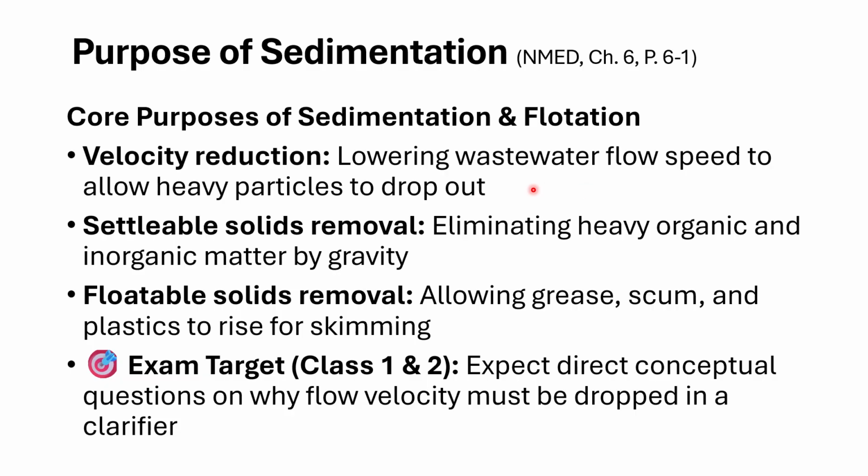And the whole idea here is we're lowering the velocity of that flow to let those heavier particles drop out. That's what a sedimentation basin does. That's what the mechanics of sedimentation do. And we're eliminating those heavy organic and inorganic matter and settleable solids just by gravity, so we don't have to expend a whole lot of energy. We're just letting that waste stream hang out in a nice still settling pond until that heavier stuff is allowed time to drop out. And that's what we would call detention time, the time that it takes for that wastewater stream to pass through a basin or a clarifier.